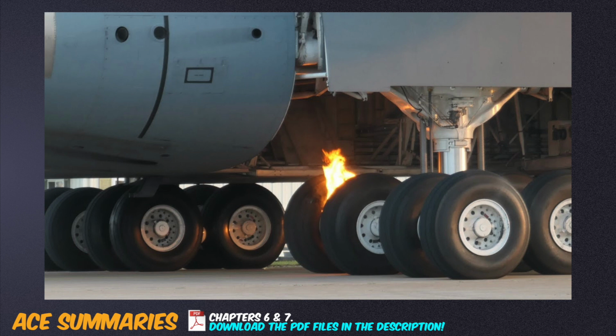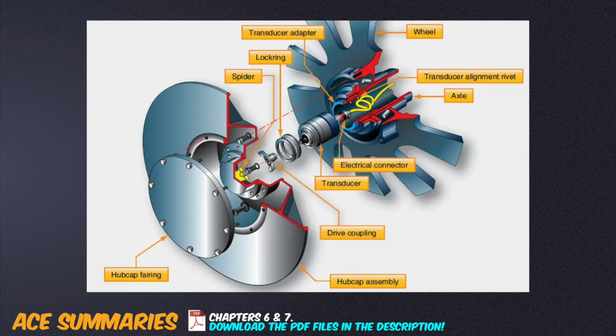With a crosswind during landing, the downwind brakes will become hottest because they compensate for the wind-induced yaw movement. The anti-skid system protects the wheels against locking during braking, skidding, or slipping. Hydroplaning is also protected against by this system. It ensures 0% brake usage at the moment of touchdown to prevent or reduce the time before the wheels are up to speed when in contact with the ground.